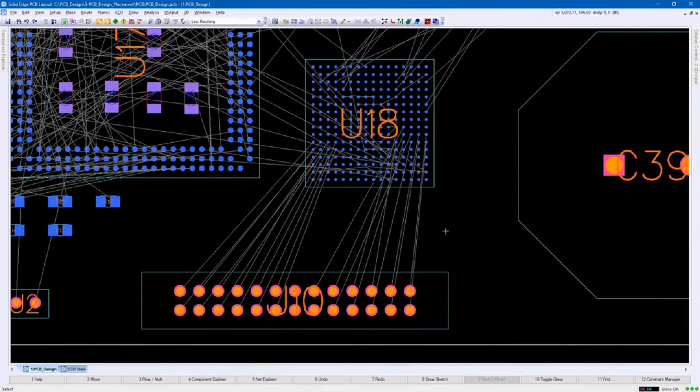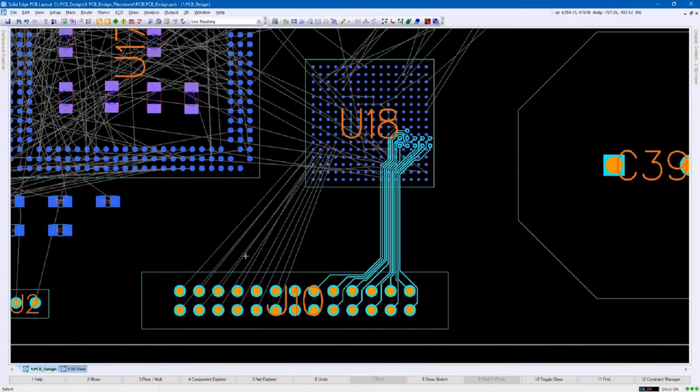When the initial placement has been signed off, the remaining components can be placed and routed. This can be done using sketching gestures, which allow small or even very large groups of interconnections to be routed fast and easily. Simply drag the cursor, and the semi-automatic algorithms take care of the rest.